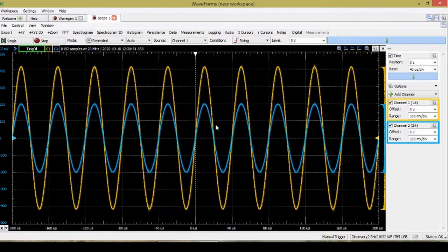In this part, it's required to measure the phase difference between the two waveforms. And as you can see, there is no phase difference between them because our circuit is purely resistive. There are no delay elements in our circuit, so all the voltage nodes in the circuit will have the same phase. There's no phase difference. So the answer for this question is 0.